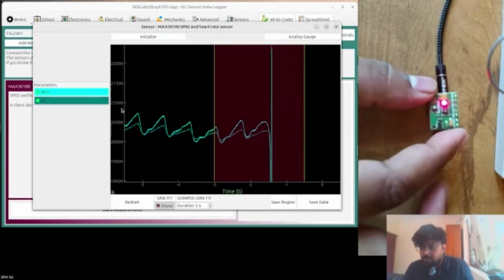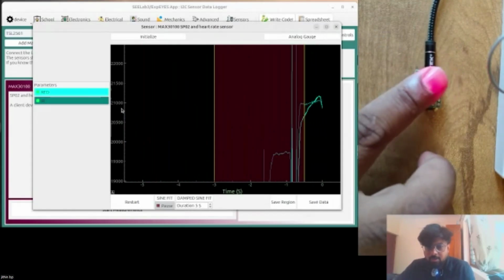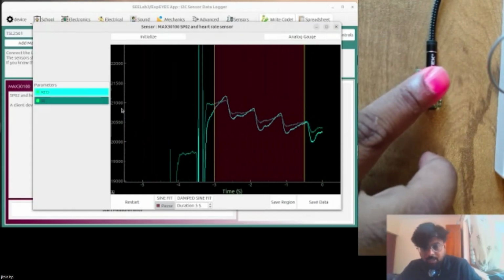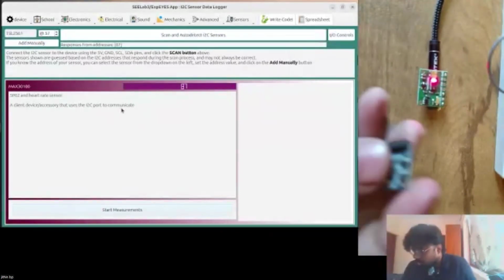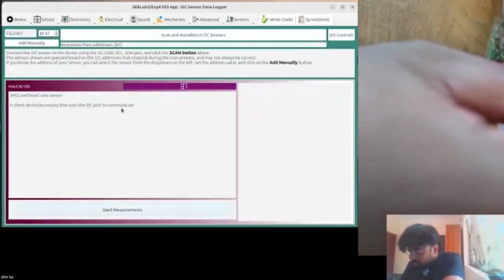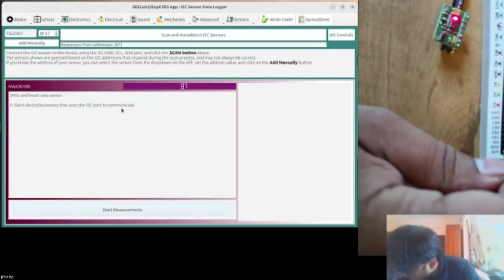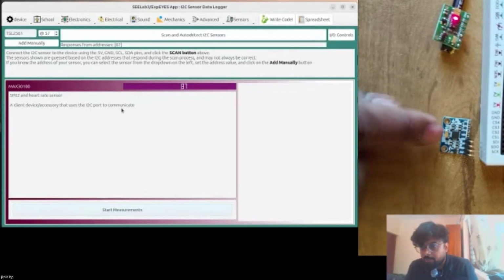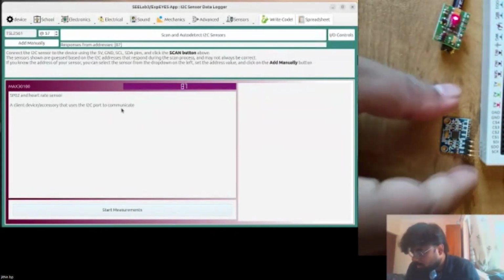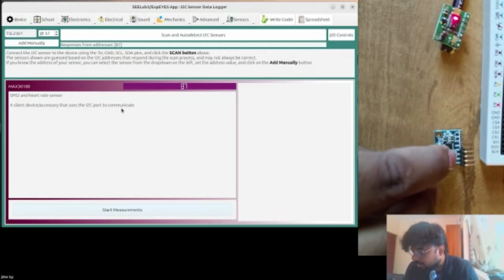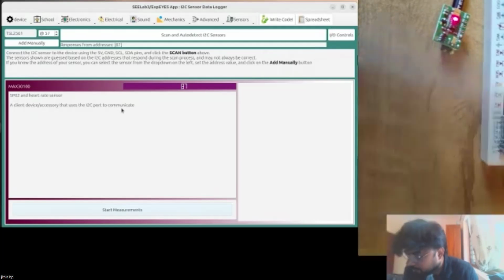Okay, so this sensor is very cheap. It's about 120 rupees or something. And you can use it for heart rate measurements. Okay, so this way, there are many other sensors. So for example, this one, let me remove all these things. Is an accelerometer plus gyroscope. Okay, this is inside all your phones for measuring the tilt of the phone. So it's got connections VCC, ground, SCL, SDA. So VCC is 5 volts, ground, SCL, SDA is here. So you can just plug it in like this here.